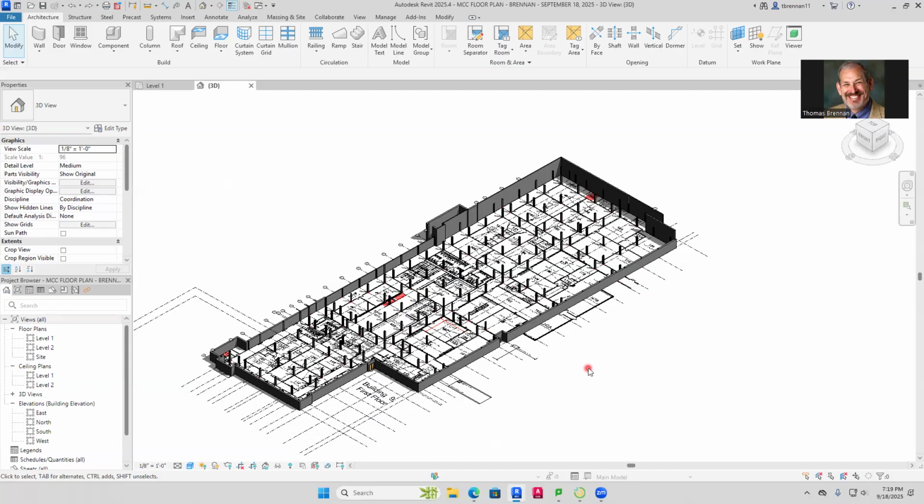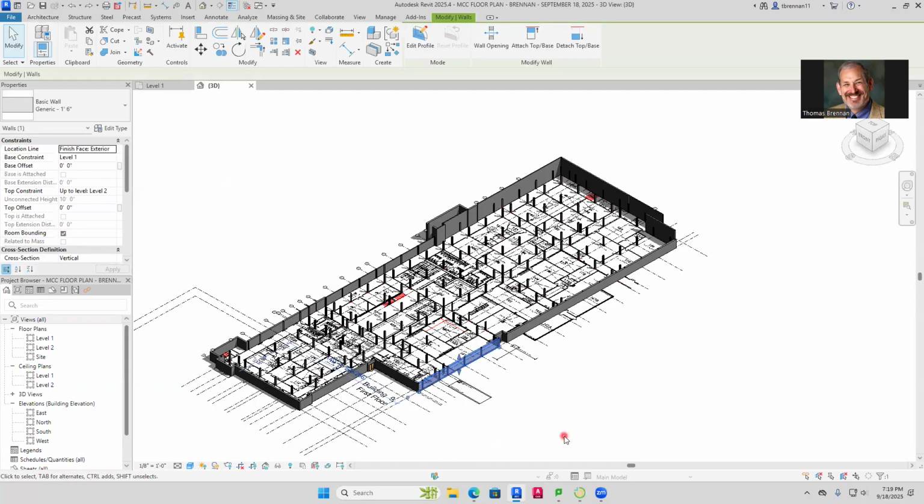Here's how that's done. In this view right here, press your escape key. Now you're going to click on any wall, and it's going to turn blue. Next, look down at the bottom of your screen and you're going to see this set of glasses right here. Can you guys see where I'm circling? All right, click on that. Click on the glasses right down here.